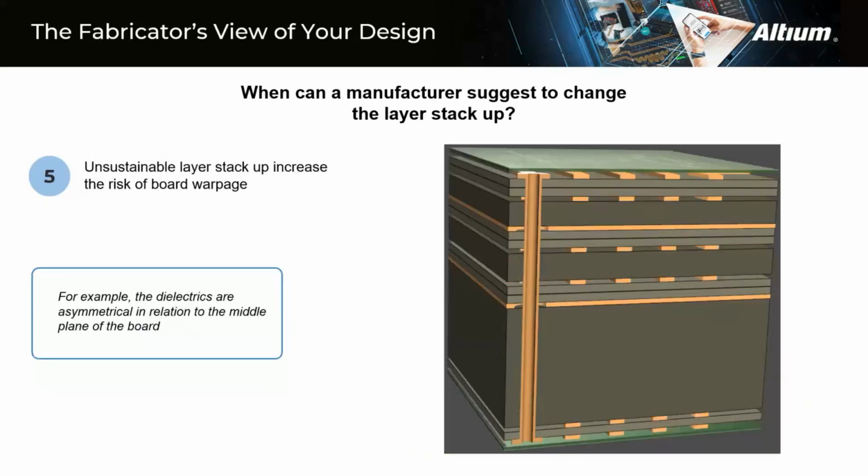Every designer has likely heard it's always recommended to design a layer stack up that is symmetrical relative to the middle plane. Deviating from this increases the chances of board warpage. In this situation, the fabricator may give designers input on the layer stack up intended to prevent the board warpage.